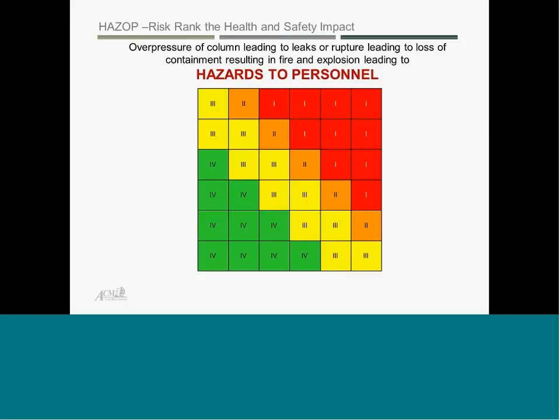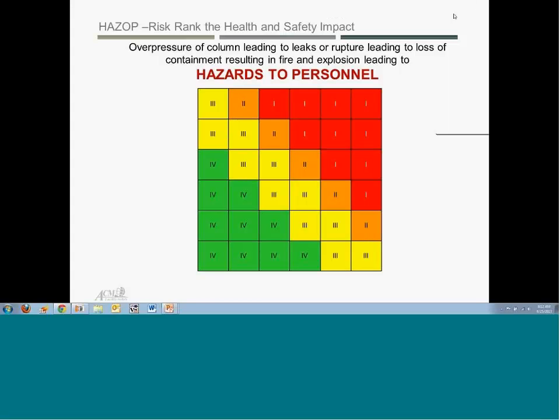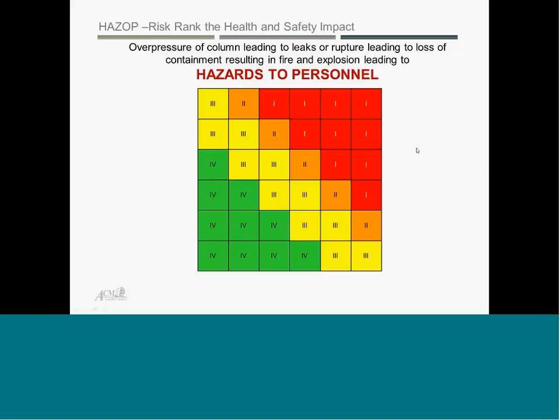So we start with a risk matrix, and this should be familiar to you if you do any sort of risk analysis. Your company would have a standard risk matrix to use. It may not look exactly like this, but it's similar. The way it works is you look at your likelihood of the initiating event here, which is losing your pump around flow. And that's going to be a number like 1 in 10 per year.